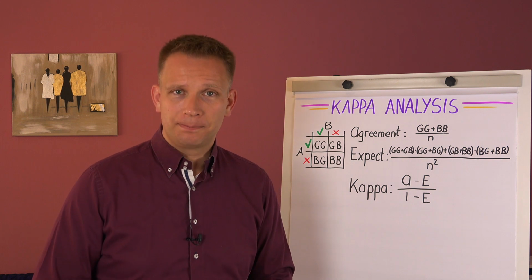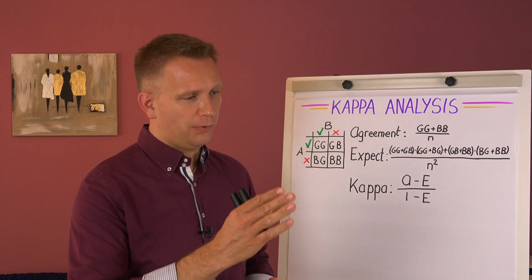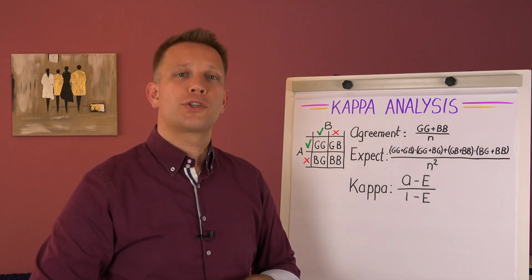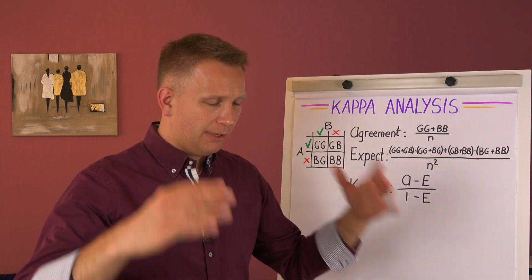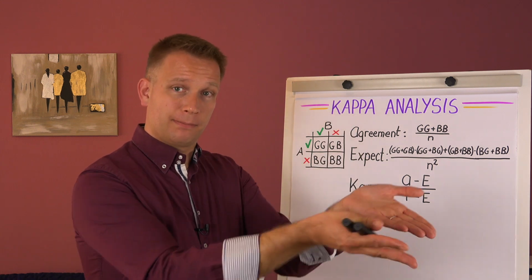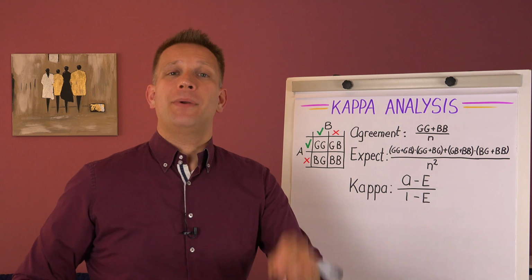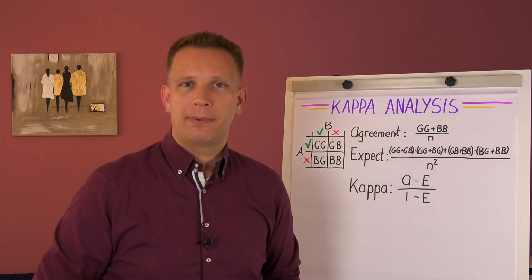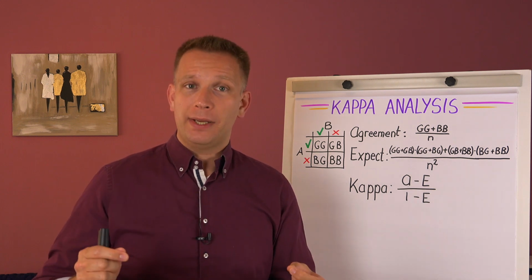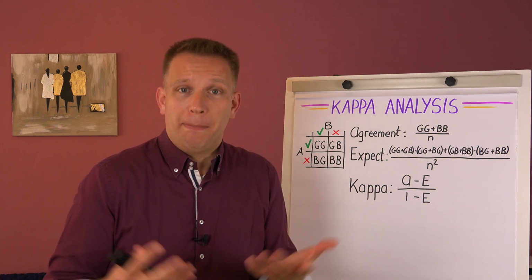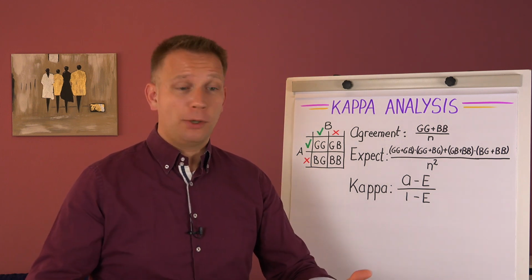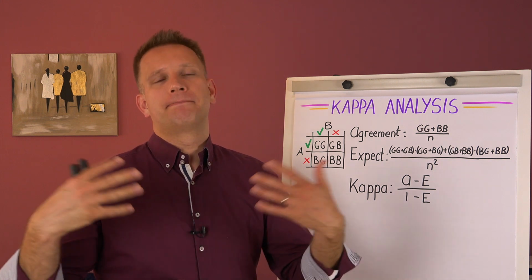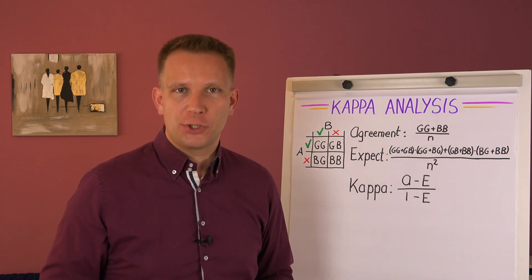In the ideal world, all of the products that operator A would set aside as good or scrap as bad, if we give those same products a bit mixed to operator B, they will pick out exactly the same products to keep in a good pile or to scrap as bad. Because that way, then we have a very good measurement system, right? So when both of the operators do exactly the same thing, we have a good trust that at least the precision of our measurement system is good.